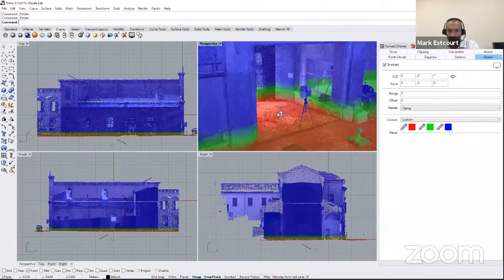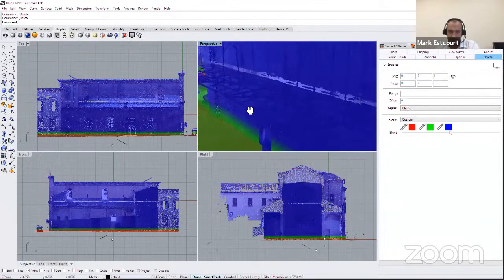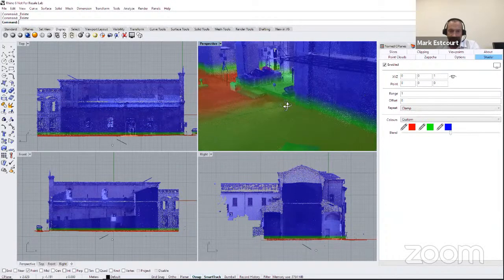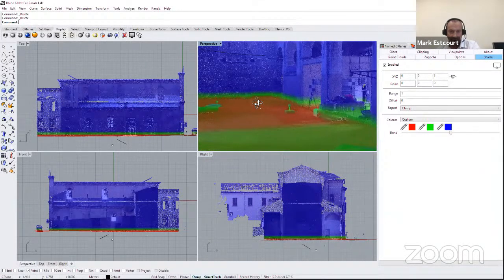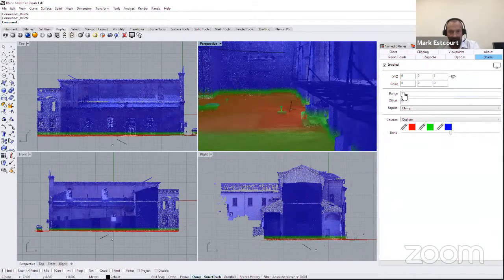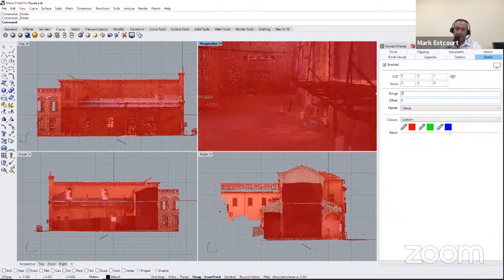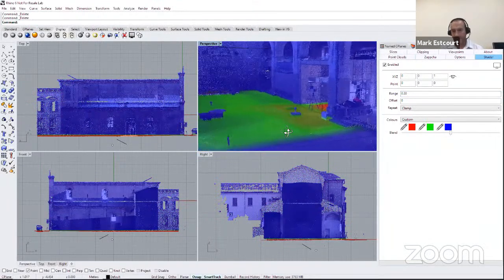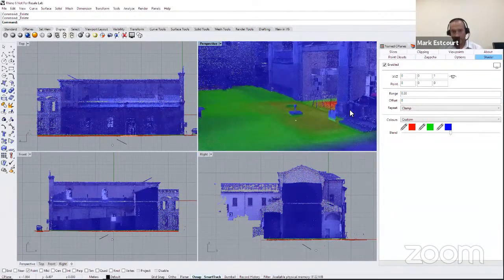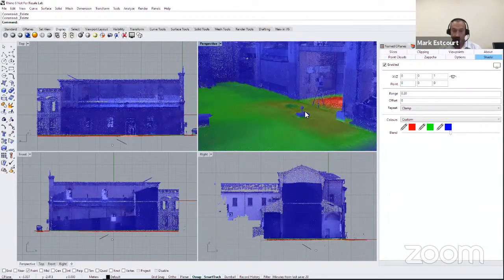So if we claim that's the floor itself, you can see by the shading change that that particular part of the floor that we're looking at there in red is lower than the green. It's a very basic example of that, but if we could change the figures associated with the ramp or the shader, you can see in more detail the gradient that the point cloud's coming down. Okay, it could be useful on roofs, could be useful on roads, all sorts of things.